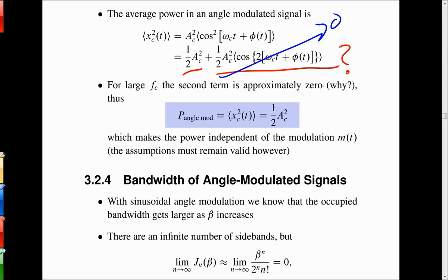And in satellite communications, constant envelope schemes have always been favored because the amplifiers that amplify those signals are usually what's called a Class C amplifier, or something that you want to run very close to the point of saturation. And if you've got a constant envelope signal, clipping or an amplifier being pushed really hard to its distortion point does not destroy the signal's integrity. Rather than the information being contained in the envelope fluctuations, it's all contained inside the argument, as the phasor frequency moving back and forth.